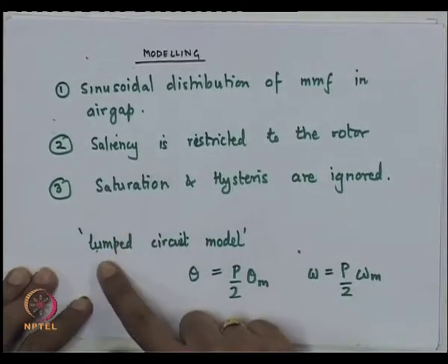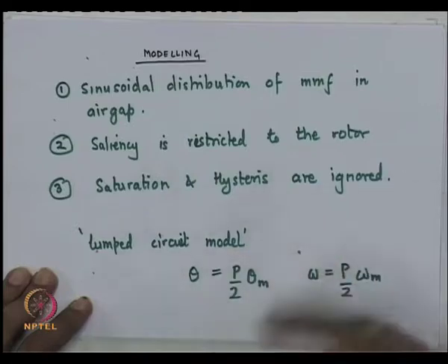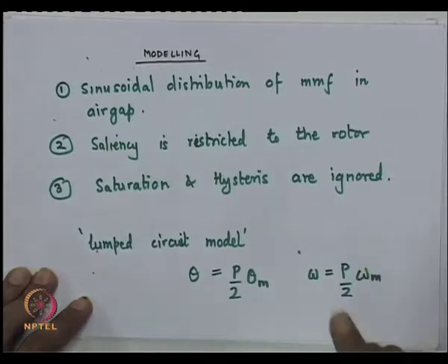And as I said, we will be getting a lumped circuit model, so we will not be modeling things like parasitic capacitances or winding capacitances and so on. So, our model is effectively restricted to the study of relatively slow transients, not fast transients.